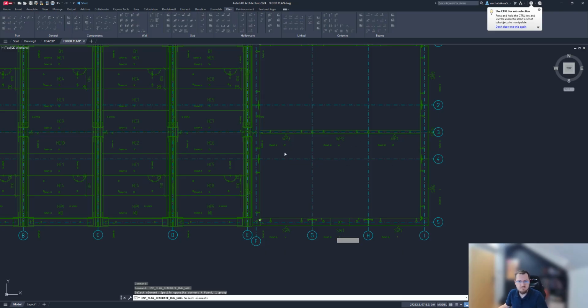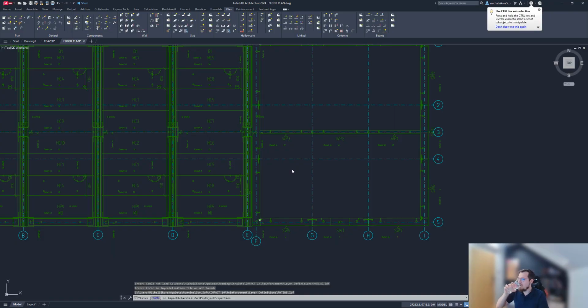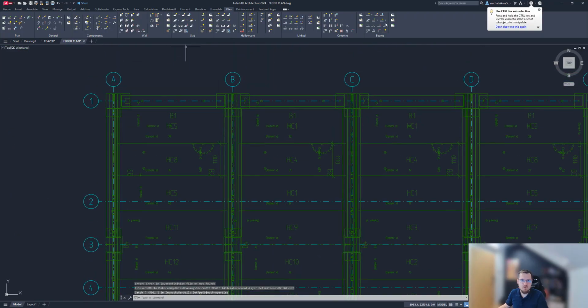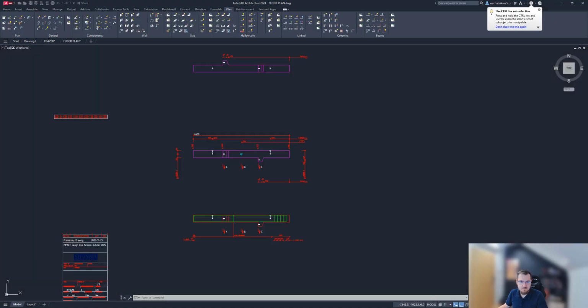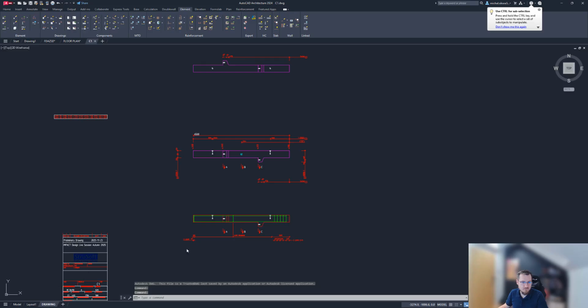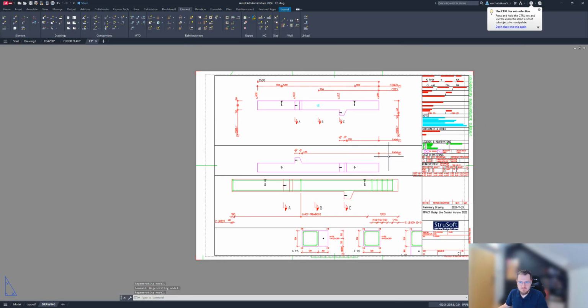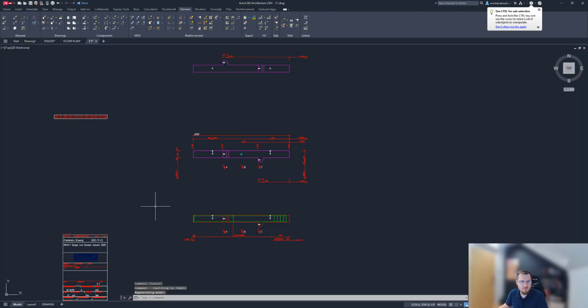First, we'll start with the column that we've added the reinforcement in, and we'll add some corbel reinforcement automatically to all the columns very quickly, like that. Let me go ahead and actually open the column reinforcement. Let's open this one in particular. Yep, we've got the corbel. We've got the drawing. Drawing is prepared for us. That's that. So that's the typical Impact drawing that you all know.